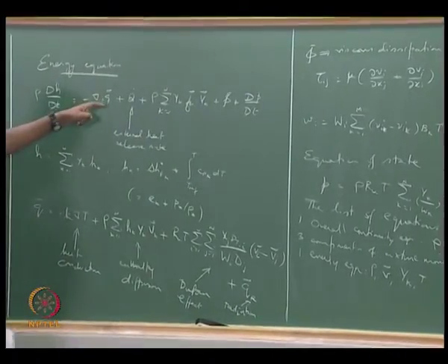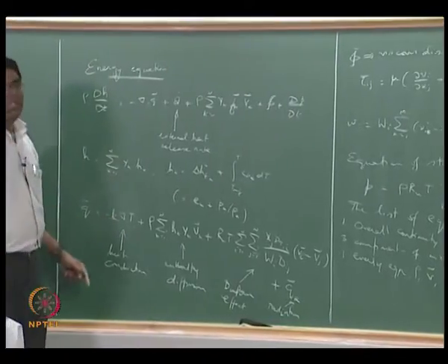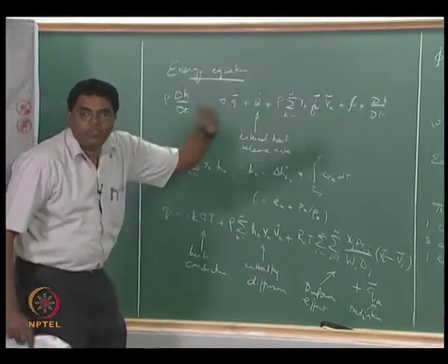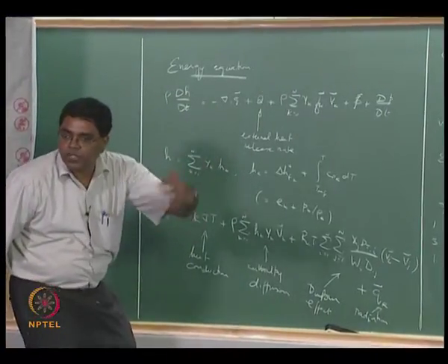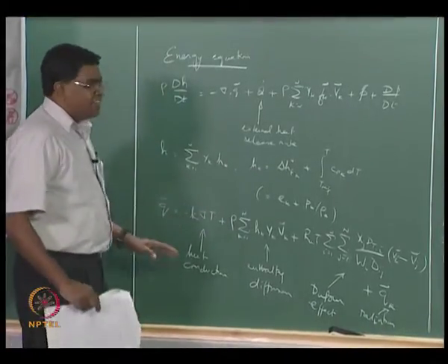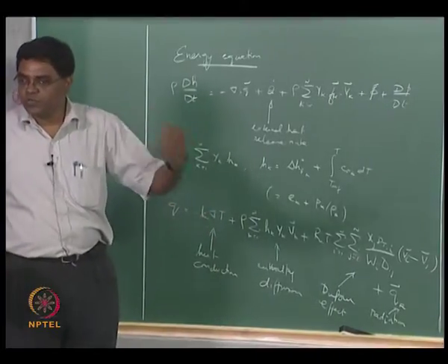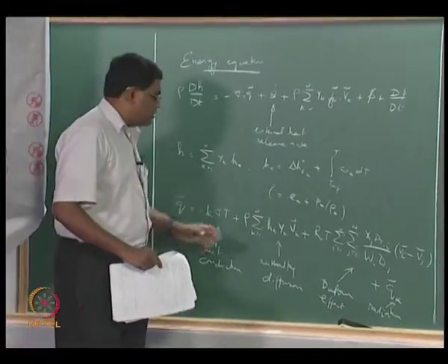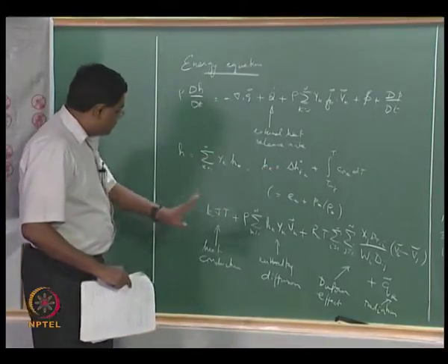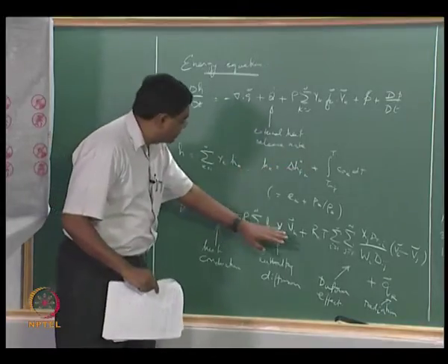So you now have Q, which has this K that's supposed to be given. Well, strictly speaking it depends on the mixture fraction, so it's an unknown, but we would then have to write equations for the relationship between the K and the mixture fraction. So you can always look at a lot of things as unknowns and then provide equations for each of those. But let's not do that at this time. T is counted, hk contains T that is counted, Yk is counted, Vk.